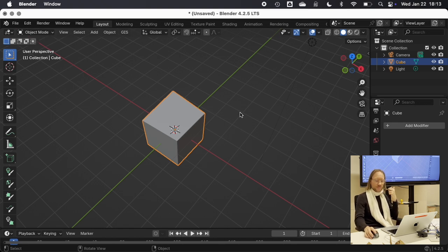Depending on the type of object, you can bring it into your computer and represent that shape in various ways. And some shapes are better with one approach than another. Shapes that are very smooth and free flowing, like this rubber ducky with a lot of smooth curvature, would be easier to represent with either subdivision surfaces or NURBS. Whereas something like this, which has very hard edges, is mechanical, with lots of different parts that come together, using a parametric model would be a better approach. And some things are kind of in between. Like this, it has a little bit of curvature, but it also has some precise features.